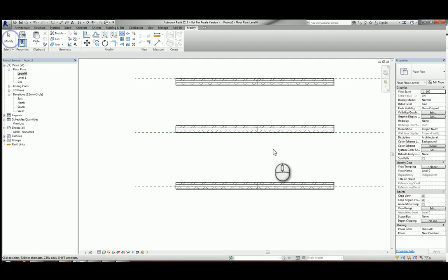Now, it's not uncommon in architecture to first of all design the building just in one wall construction, and then after that say, right, that facade looks a little bit plain, what I need to do is put some rendering in there. We'll just put like a render strip in there. So this is what I'm going to do just here. I'm actually going to swap these walls out for a different construction, which is very, very similar structurally. The plasterboard is going to be the same, the structure is going to be the same as in the masonry concrete blocks. The cavity is going to be the same, but then instead of having 102.5mm brickwork, we're going to have a 75mm block with 22mm of render on it.